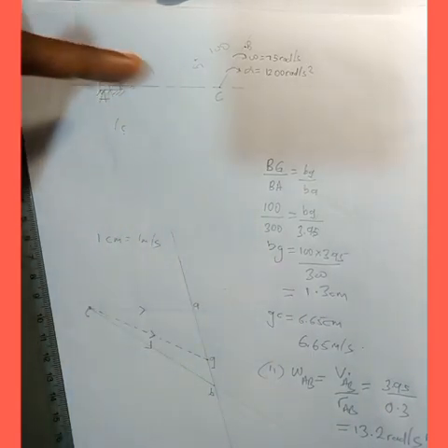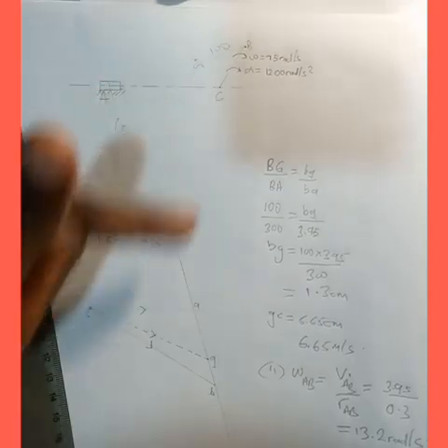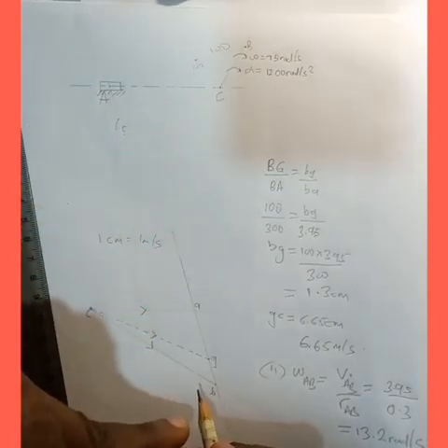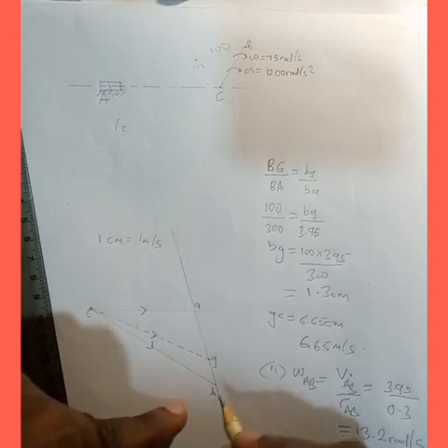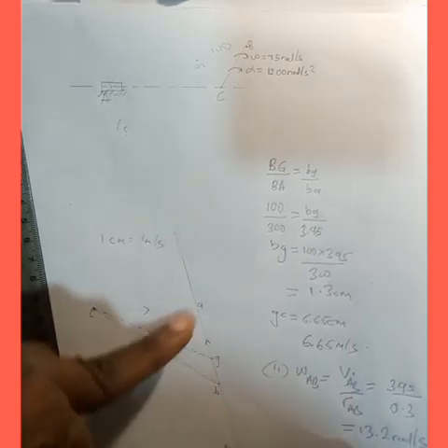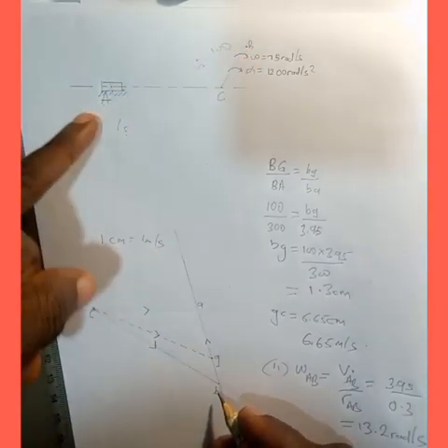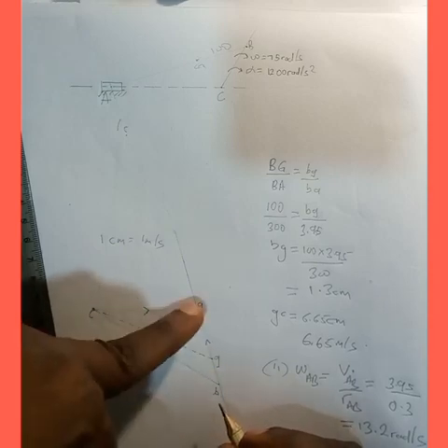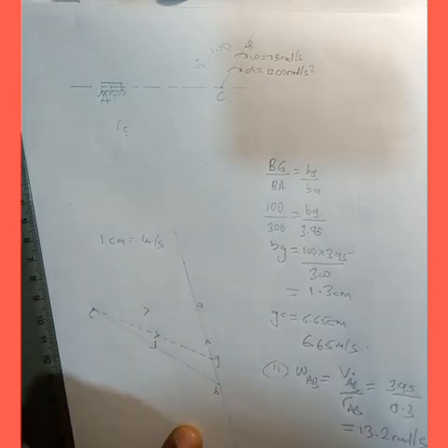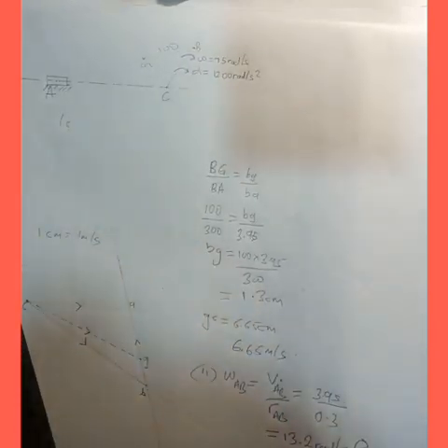That's going to be in the clockwise direction about center B. Now looking at the configuration diagram, B is the center to A and C. Looking at the velocity diagram as well, the direction of the arrow is going to be from B towards A, because we are going to find the velocity of A with respect to B. B is the starting point, A is final. So that's why the direction of the arrow is this way. Now we need to find the third and the fourth solutions. The third one, we are expected to find